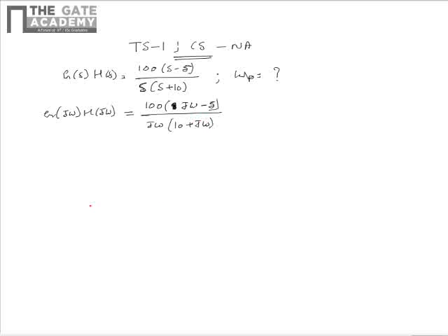We know that at the phase crossover frequency of a control system, G(jωp)H(jωp) will have the imaginary value as 0. That is, at phase crossover frequency of a control system, the imaginary part of G(jω)H(jω) is 0.